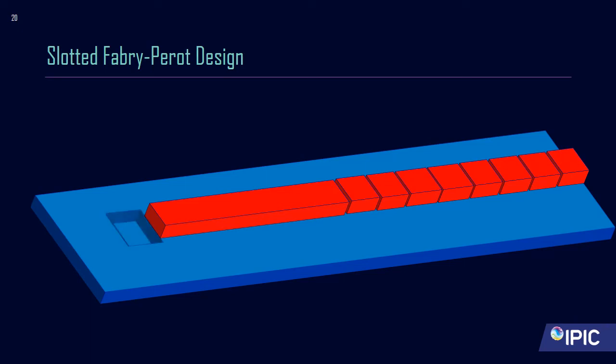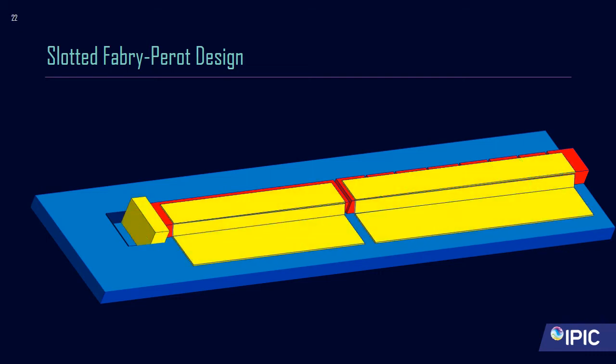Then you etch further at the end. This is to create the metal etched facet by adding the metal, as so. So the metal etched facet here allows light to be confined better within the Fabry-Perot and the slots. Then there's a cleaved facet here where you can measure it out. Also, oxide and metal is evaporated onto the top and sides. This is to create contact pads, so it's easy to probe the laser and send current through it.